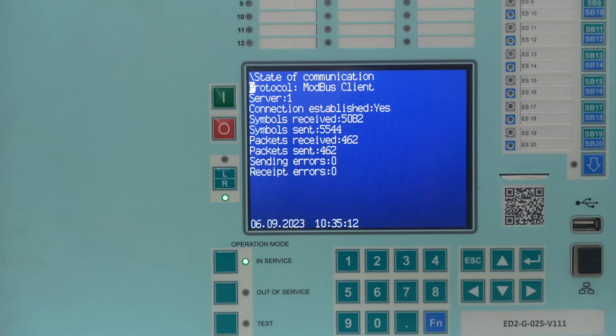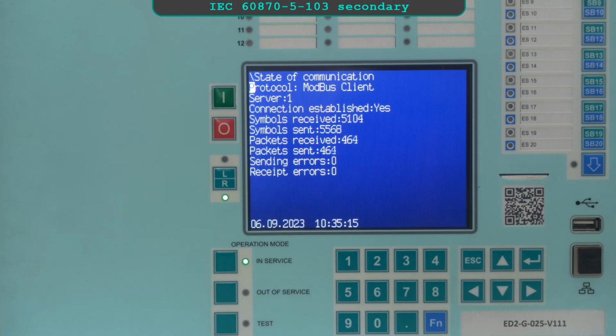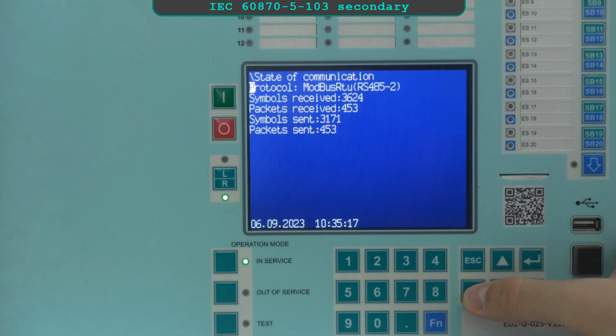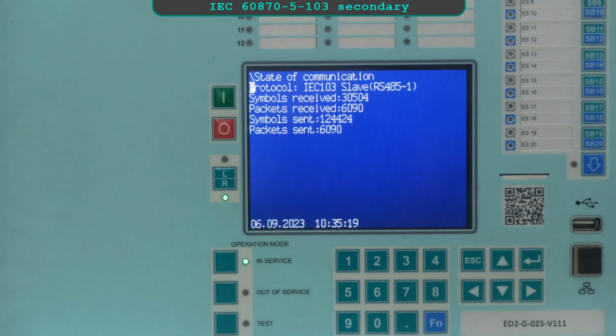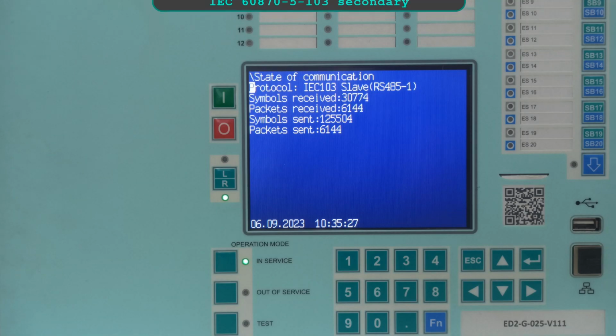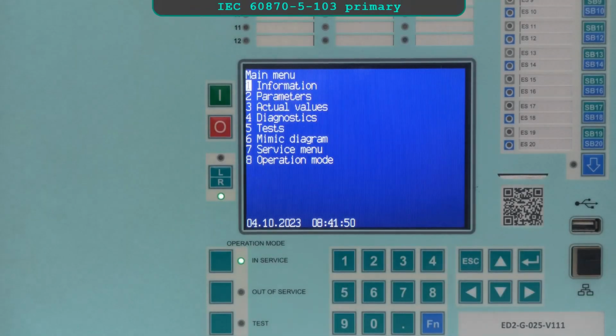protocols. For diagnostics of data transmission via IEC 60870-5-103, move to the relevant protocol. The statistics on data transmission, possible reasons for no connection, as well as ways of troubleshooting are similar to those described for the Modbus RTU diagnostics. Note that the IEC 103 Master Protocol Diagnostics is made only through IED display.